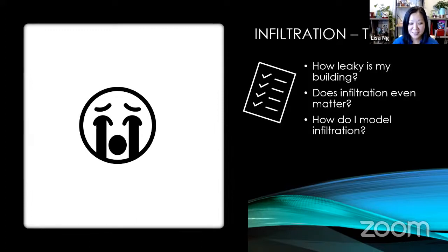Yeah, so I'm at PHIUS, formerly the Passive House Institute US. So anybody who's familiar with passive building knows we're a little nuts about infiltration. Most of our stuff, we end up using a monthly model that sort of follows that divide by 20 rule of thumb. But recently we've been doing a lot of research into thermal resilience. So in EnergyPlus, I've read Lisa's paper on the commercial flow and one of the other models in there, and ended up going down a rabbit hole and figuring out that the flow coefficient model works best with the data we have available, which are those blower door numbers that are fairly easy to convert.